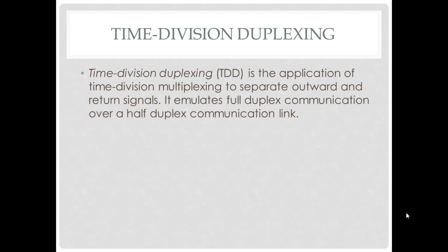Time division duplex refers to duplex communication links where uplink is separated from downlink by the allocation of different time slots in the same frequency band. It is a transmission scheme that allows asymmetric flow for uplink and downlink data transmission. Users are allocated time slots for uplink and downlink transmission.